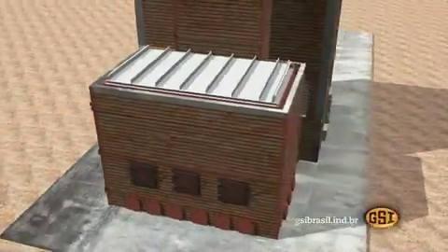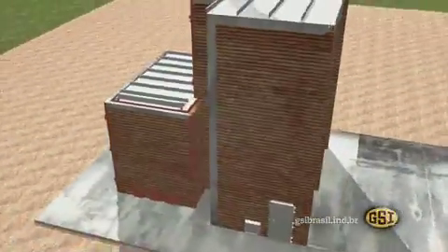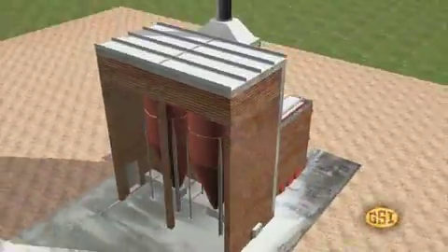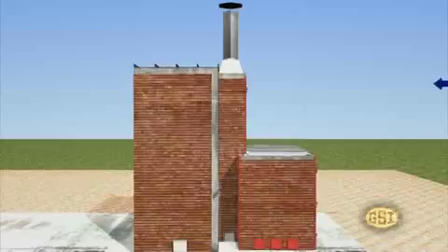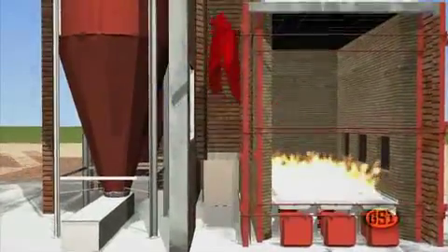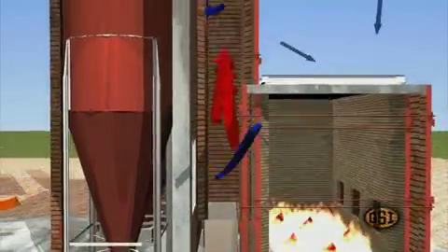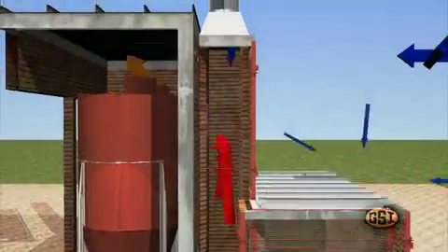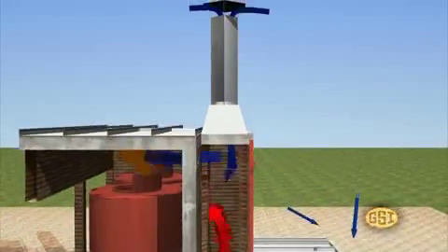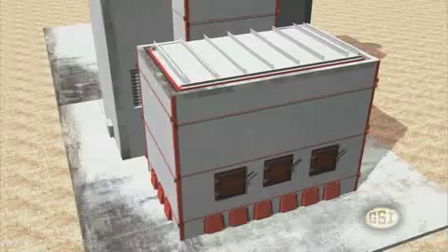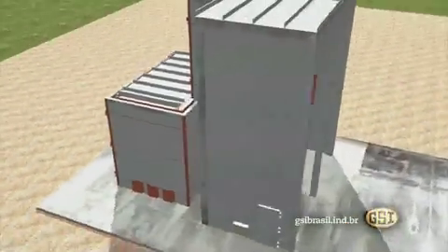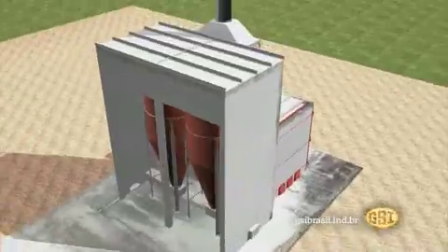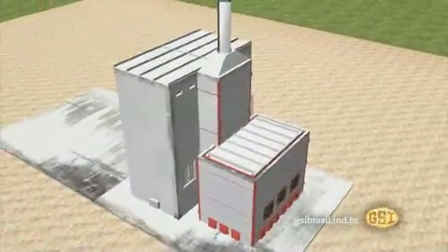Furnace. The furnace of the process dryer allows better use of thermal energy with maximum combustion of biomass gas. The unique structure of the furnace and internal temperature of up to 700 degrees ensures clean and warmer air for the drying process. Cleaner air, more valuable grain. Only about 10% of the air used for drying comes from the furnace.